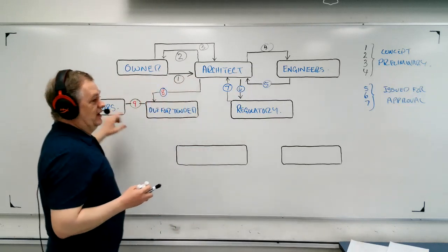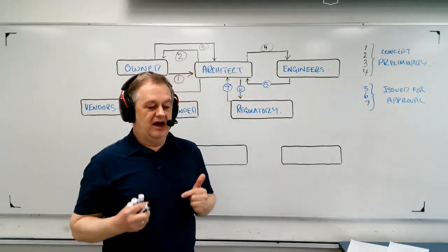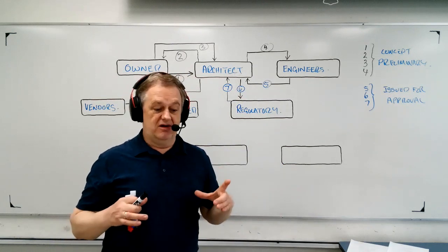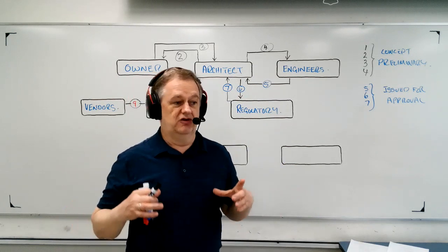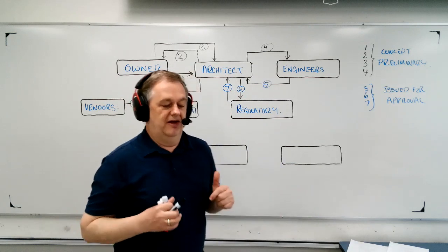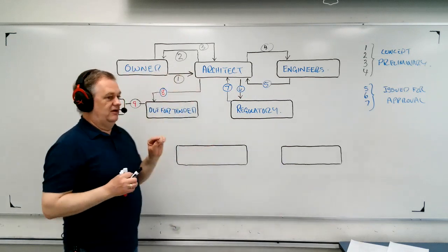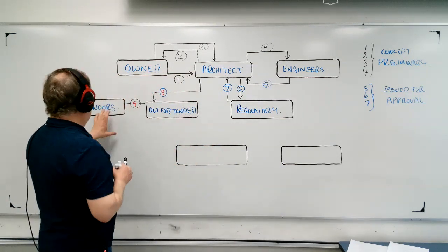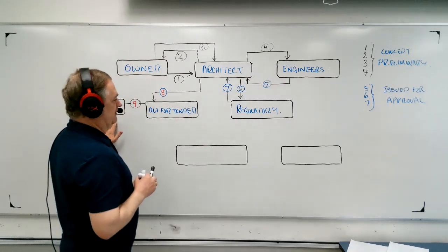The vendors who actually are going to provide the equipment now have to provide a plan that will become part of the overall set of construction drawings if they get the job, okay? And those plans are very, very specific plans that are called shop drawings. And the shop drawings give all the details of the equipment that these vendors are going to supply.